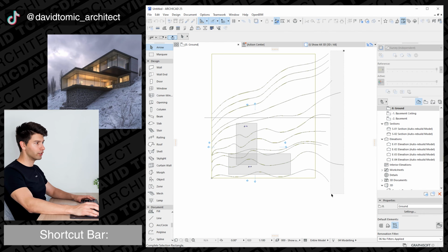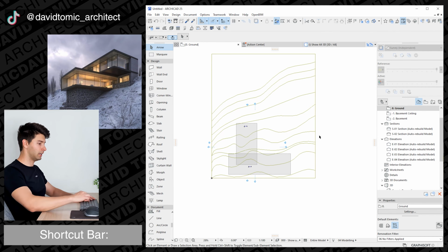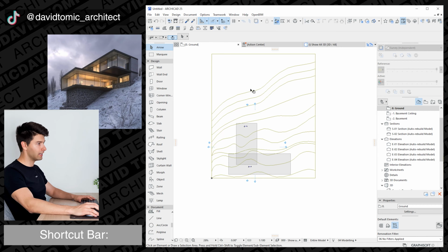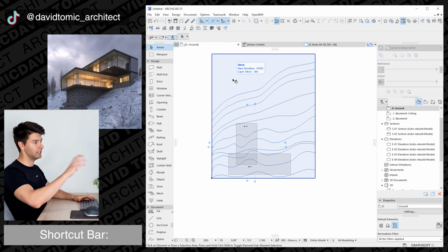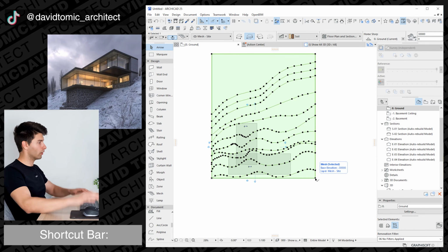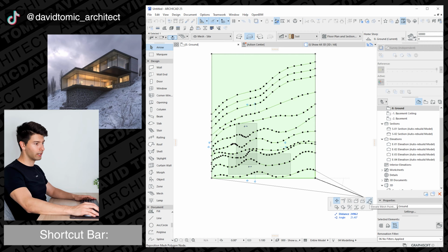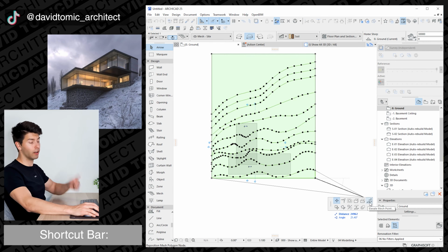Now that we have all those points created, we can simply select all those splines, delete them, again, delete that spline there, and then start manipulating this entire surface here. So if we click on that mesh again, let's pick our first corner, which is going to be a dead flat line across the front. We're going to click on this corner, and then we're going to come across to this elevate mesh point, which looks like a line with a Z on it.